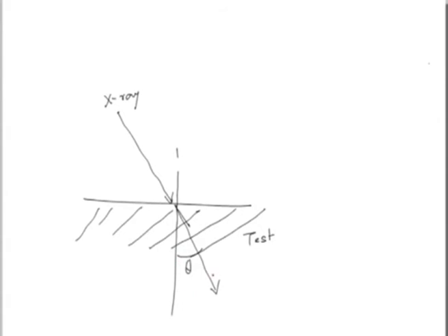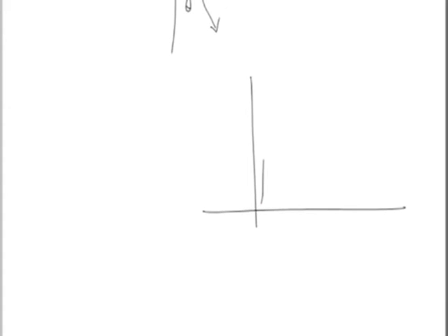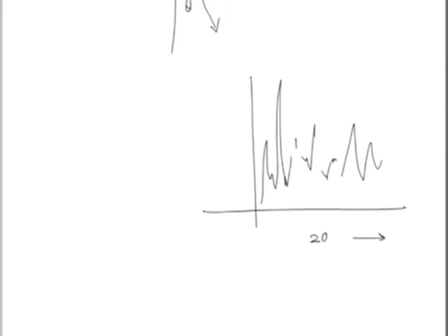That means this diffraction will be characteristic of the material or the crystal structure through which the incident X-ray is passing through, and therefore, we can get a signal like this. So, here this is 2 theta and this is called intensity. Now, these different peaks represent that one element, say E1, is present, and that can be confirmed by subsequent detection of 5 such peaks in this spectra.